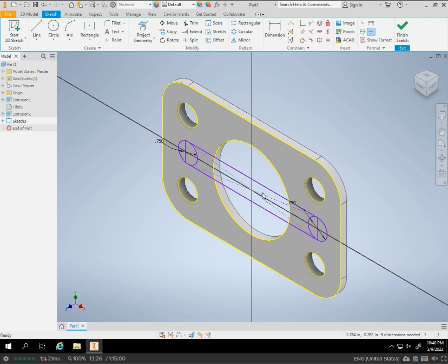All right, so by doing the center point circle from the middle, once I touched and locked into one of the tops of the circle, it automatically locked the rectangle into the bottom and the top on the opposite side. So that actually kind of worked out really well.